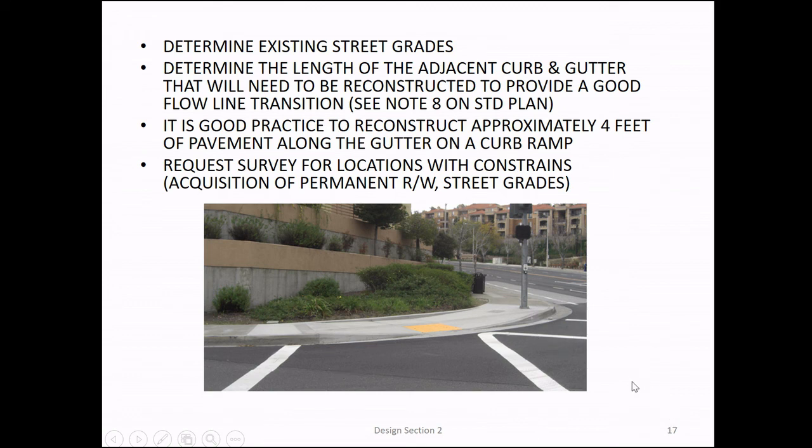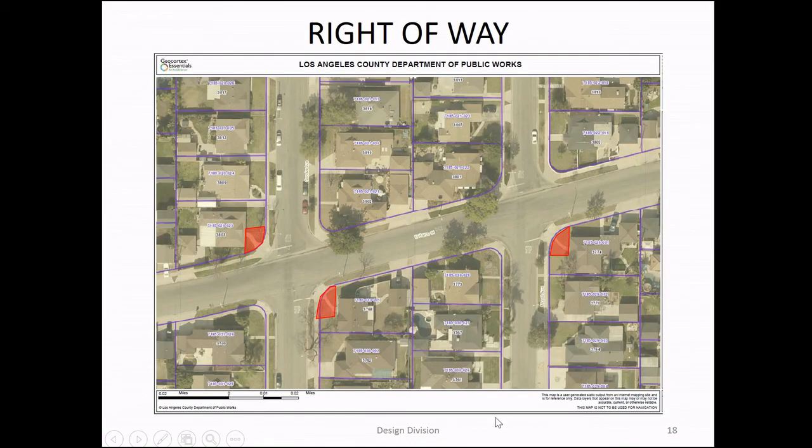Because you still have to have your 4 feet. And if you have a crosswalk, you need to have 4 feet from this point to your line, if it's striped. What if it's not striped? Then there's no crosswalk, so you can push it further. Okay, so guys, just make sure you get on it right away, because this could impact your schedule when you have situations like that.